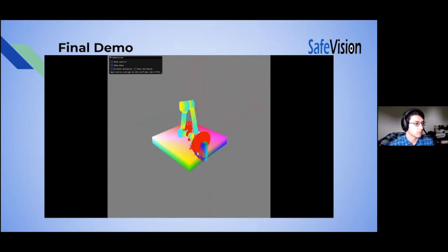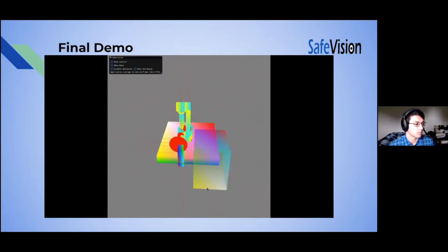First, the arm moves to its starting position. Then, obstacles are placed in the simulation, and finally, the arm moves to its end position and may or may not stop. In the test just shown, the arm correctly stopped because a sensor near the head of the arm detected a nearby obstacle. In this next test, the arm starts very close to an obstacle. However, because the arm moves away from the obstacle and isn't in danger of colliding, the arm doesn't stop.